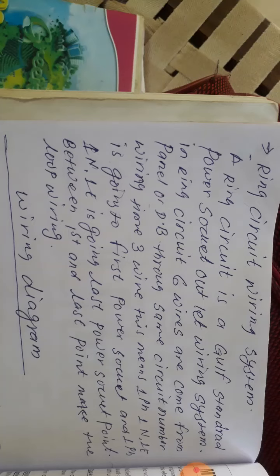In our area, in our country, we use the same circuit for lighting and power, but this is not standard wiring. In standard wiring, lighting is one circuit and power is another circuit. Especially in the Gulf, 2.5 mm square wire is used for lighting purposes. They do not use 1.5, only 2.5 to start. 2.5 mm square wire is used for lighting, and 4 mm square wire is used for power socket wiring,